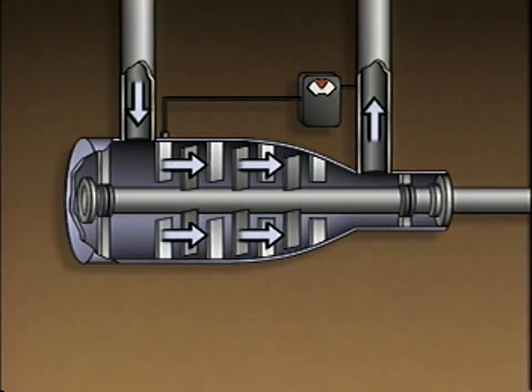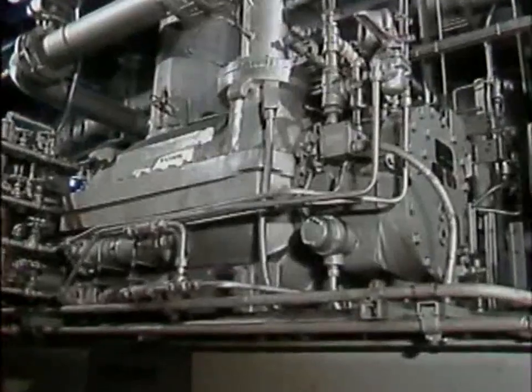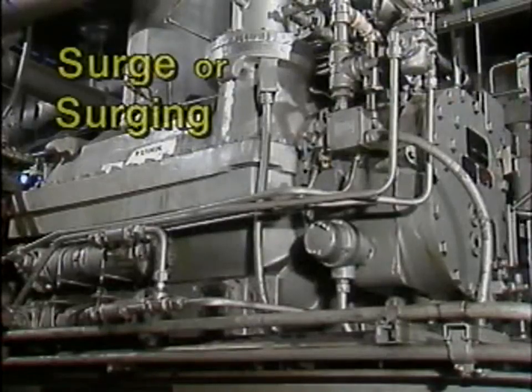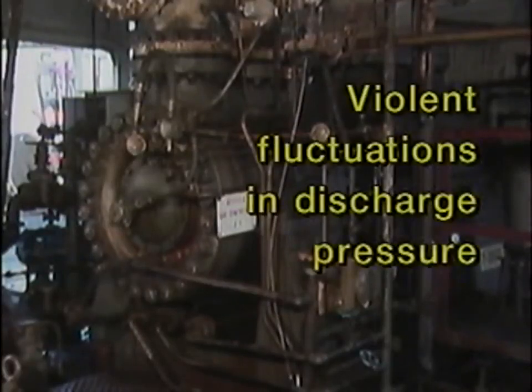For a given discharge pressure, a compressor has a certain minimum flow rate. Below this flow rate, the compressor becomes unstable. A decrease in flow below the minimum flow rate can cause a series of momentary reversals of flow through the compressor. This situation is called surge or surging. The symptoms of surging are unmistakable. Surging results in violent fluctuations in discharge pressure.